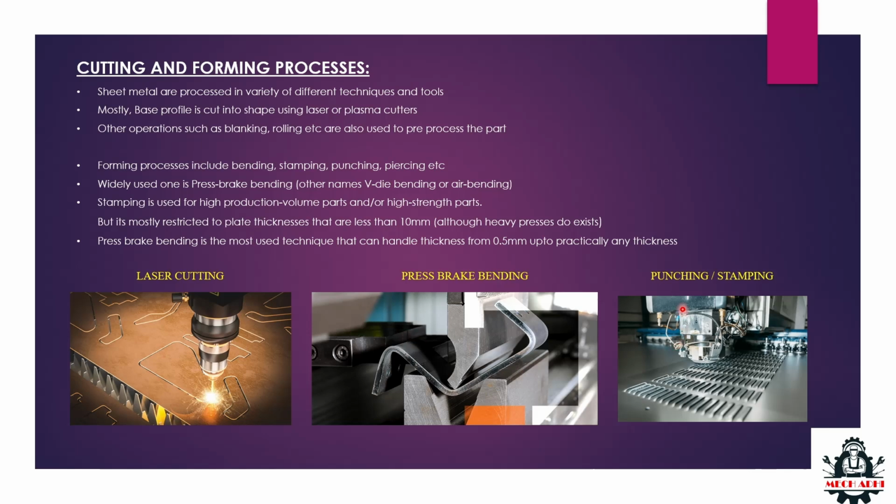And then coming to punching and stamping, these are extremely design dependent and are costly methods that involve a lot of tooling. And of course, there are some conventional stamping and punching processes such as punching louvers, where there is not necessarily a material removal, but these are used for airflow, or sometimes they can also act as stiffeners on your design. In case you're not having any external stiffening member or a gusset, these stampings could very well act as a stiffener and also a facilitator for airflow, which you might have seen in some places around you.